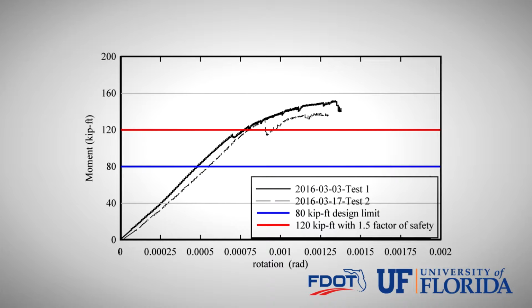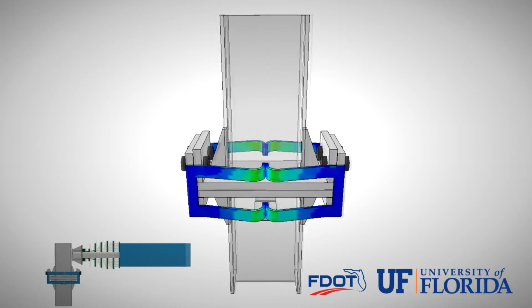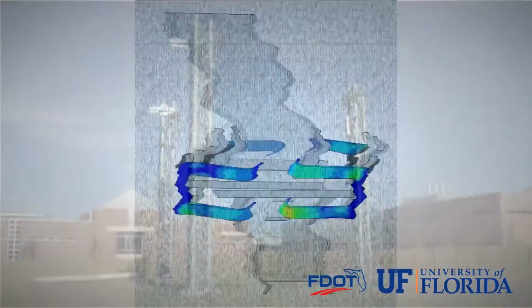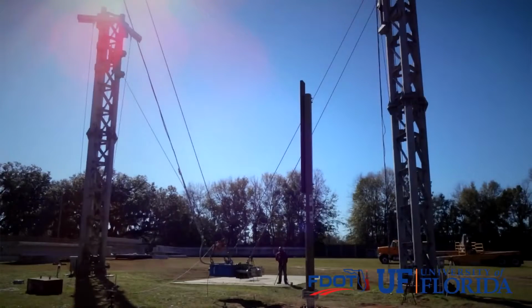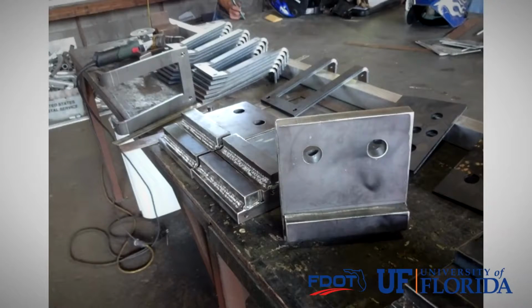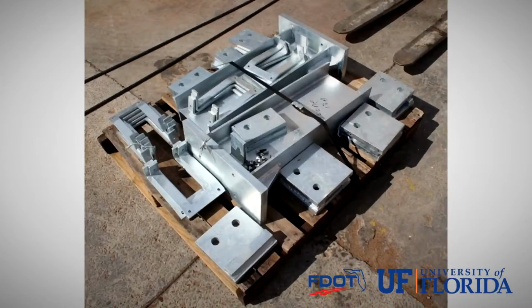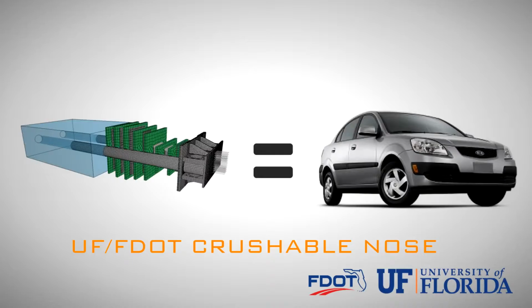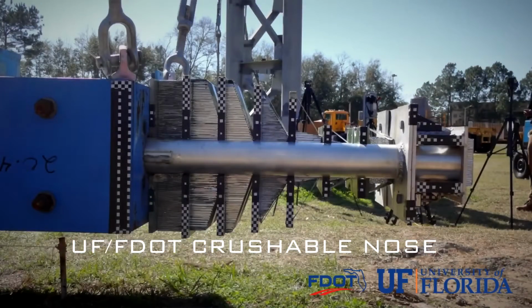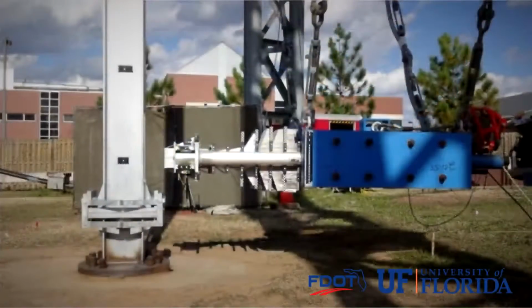the design wind loading. To evaluate the breakaway performance of the system under impact conditions, dynamic physical tests were conducted at the Florida Department of Transportation Structures Laboratory using a gravity pendulum facility designed by Dr. Gary Consolazio and Dr. Long Bill. Evaluation of the breakaway systems required multiple tests. To make this possible, a cost-effective surrogate vehicle designed to recreate the crush behavior of a MASH-compliant Kia Rio, also known as the UF FDOT crushable nose, was designed by Dr. Gary Consolazio and Matthias Gruters.